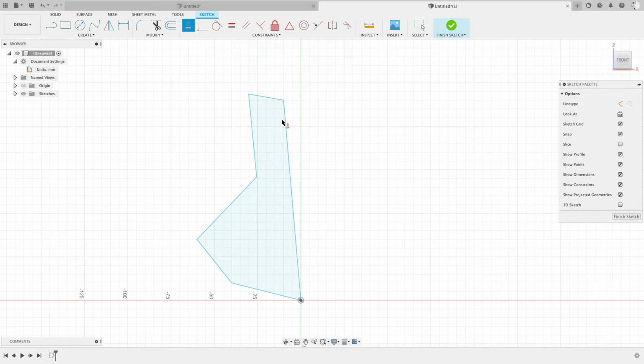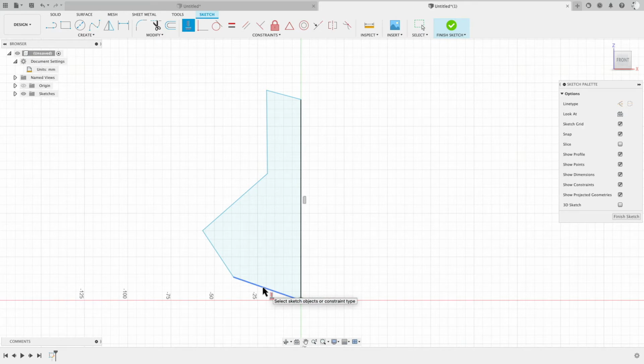Constraints, vertical, click. This I would like to be horizontal, click, horizontal, click, vertical, click. And the software understands if the line is more vertical, then it's vertical. If the line is more horizontal, then probably we guess, the software will guess we want this to be horizontal. So this is vertical, good, undo